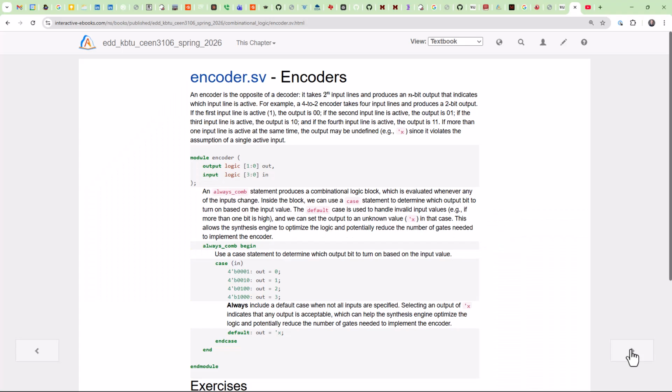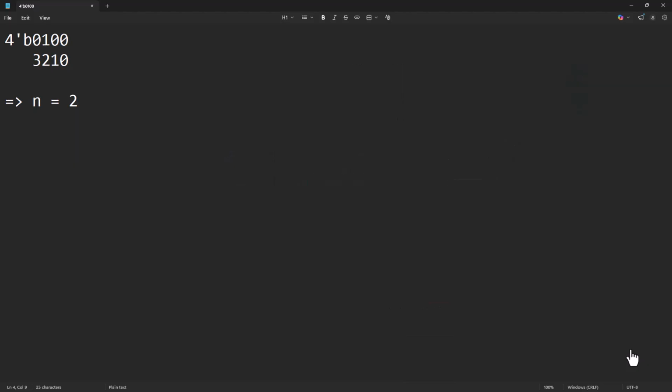It brings up a couple interesting questions. One is, what should we do when we have something that doesn't follow our pattern? For example, what if we had an input like this, where instead of having just 1 bit on, we have 2 bits on? What should we produce as our output in this case? This is where we can assign a default value or provide an initial value.